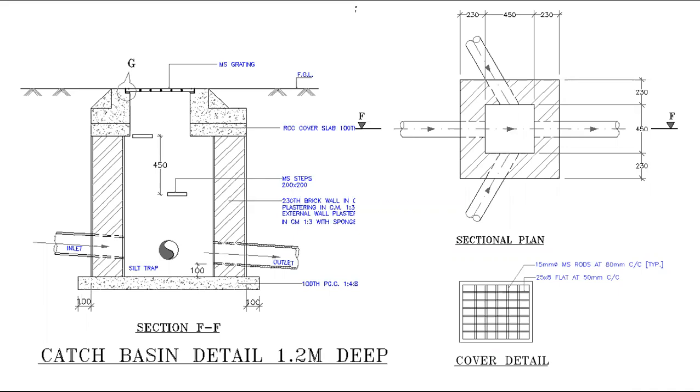But if we don't get floor space to place the grease trap, then what is the solution for that? If you don't have floor space, you can give a ceiling-mounted grease trap also, but you have to check the size of the grease trap. Okay, so can we place it below the basin or sink? Below the wash basin you can use it. For the kitchen area, below the wash basin and below the sink also you can give it. Okay, you can place it.